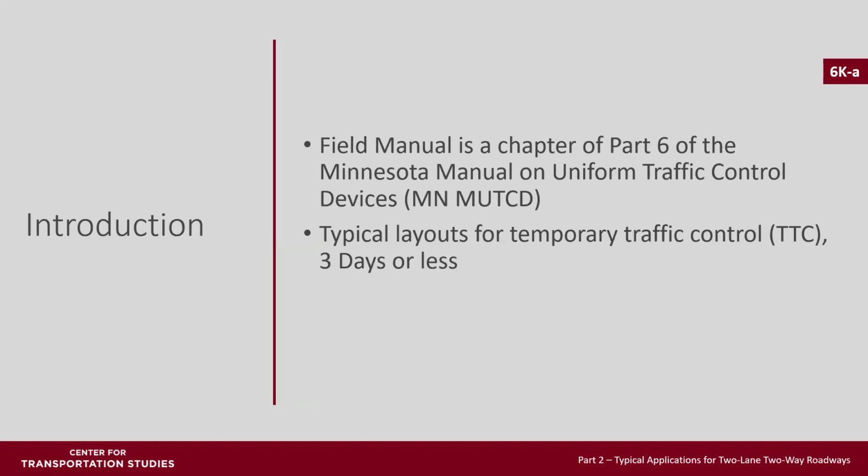It must be remembered the goal of temporary traffic control is to provide for the safe and efficient movement of traffic around a location where the normal function of the roadway is temporarily suspended. To accomplish this, the respect of the driver must be earned by appropriate and prudent use of traffic control devices. When work is not in progress or the hazard no longer exists, the temporary traffic control shall be covered, turned away from traffic, or removed from the area. Very important to earn the driver's respect.